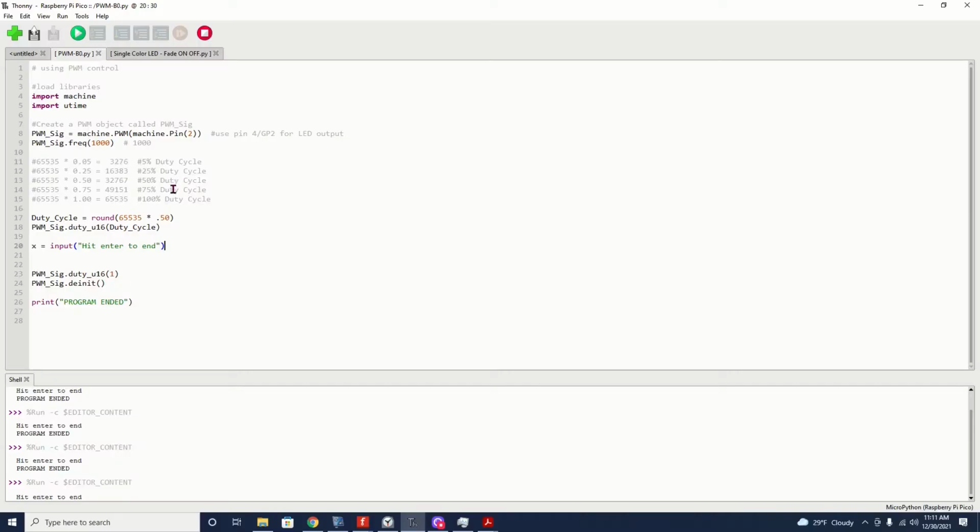Now we can take a look at the program itself. Now we're going to load a couple of libraries. Import machine is the machine-specific library for how MicroPython deals with the unique differences between each type of microcontroller, such as a Raspberry Pi PICO or an Arduino, etc. UTime is the library for your time-based stuff, and in this particular part of the program, we're really not utilizing it, but we will in further iterations. Now, UTime is identical to time, except it's the MicroPython version of it.